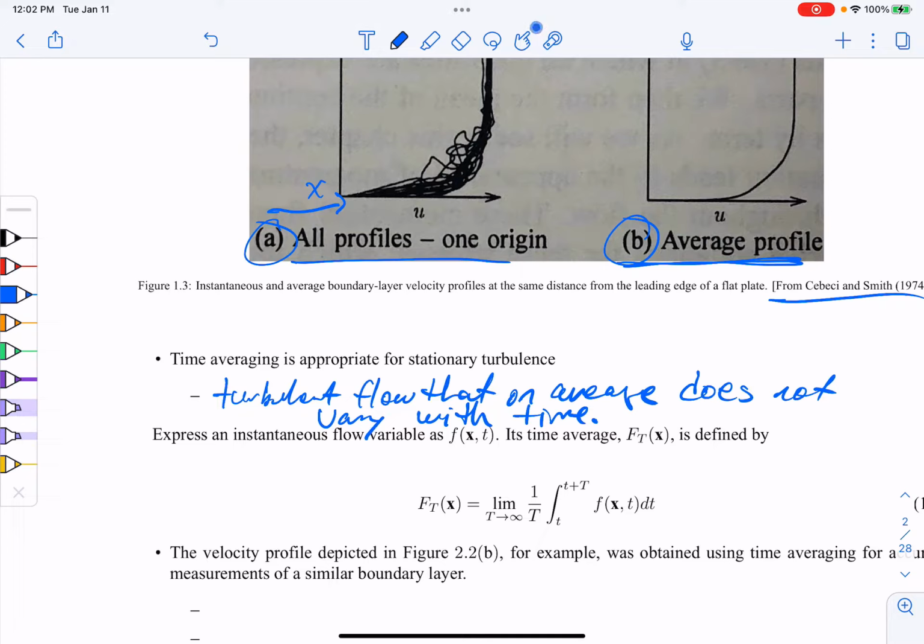And maybe you can give me an example. There's lots of examples of turbulent flows which are statistically stationary. So if their time averages are the same today or tomorrow, but at any instant they're always different. So anybody want to share an example? A jet flow. Yeah, so a jet flow, if it's running like in a rocket engine or a jet engine, my throttle's at the same position, the same value, then the flow would be statistically stationary. Boundary layers, Couette flows, swirling flows, shear layers, backward-facing steps. These are all statistically stationary, but at every instant of time, they have a different realization of turbulence.